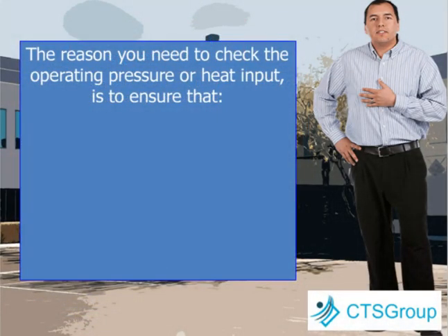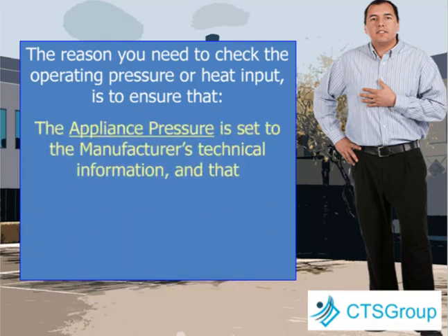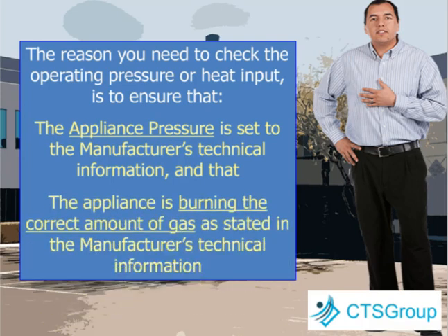The reason you need to check the operating pressure or heat input is to ensure that the appliance pressure is set to the manufacturer's technical information and that the appliance is burning the correct amount of gas as stated in the manufacturer's technical manual.